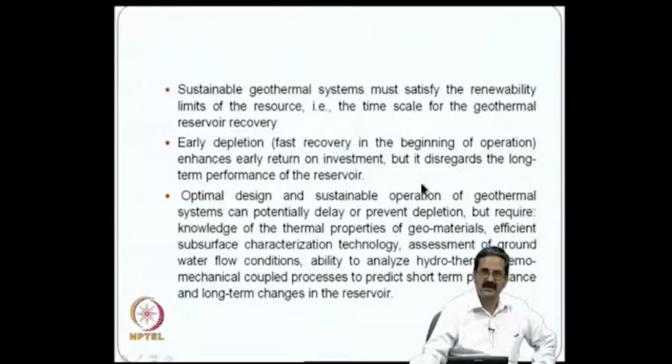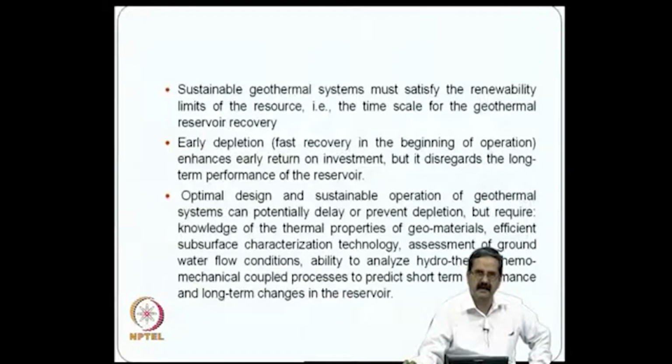And what I want to say is that these are all the areas that are governing the future. So, all geotechnical engineers or ground improvement engineers should look at such devices. Say if somebody is going for piles as a source of energy, like I said, thermal piles. Using stone columns to improve the bearing capacity is one thing, but using a steel pile or some sort of thermal pile and then trying to recover heat or bring heat to the ground is something that is very innovative. So, one needs to understand a lot of dynamics.